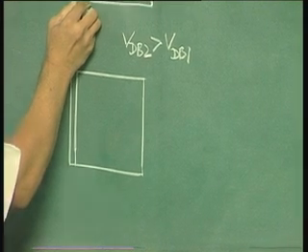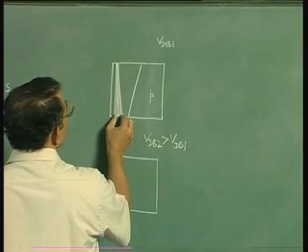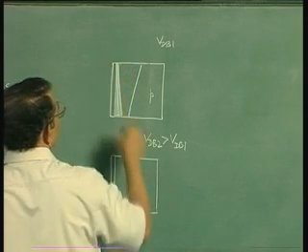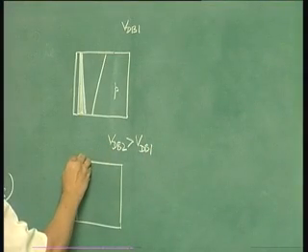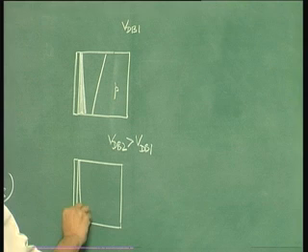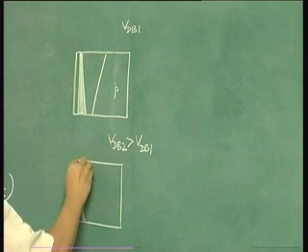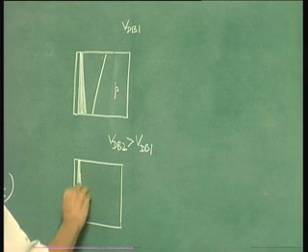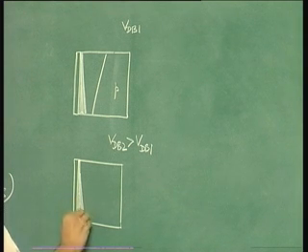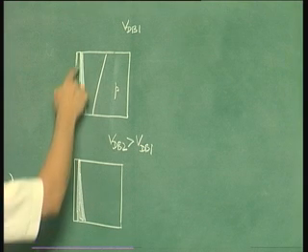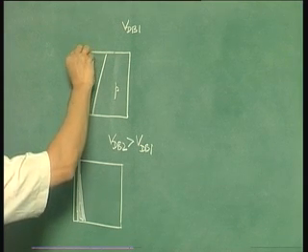Notice that the charge at the source will not change because your source to bulk voltage is not changing. Only the charge at the drain will become even less because the voltage is more. So something like this. So this charge at the drain is less than this charge.